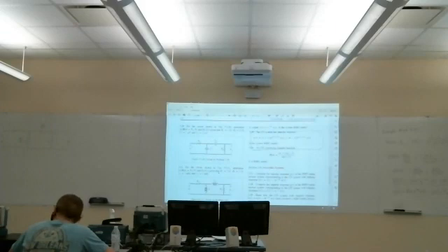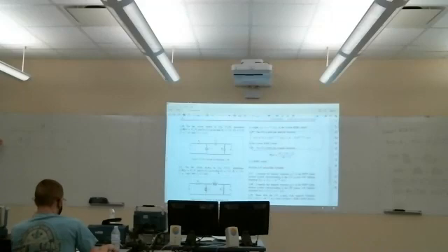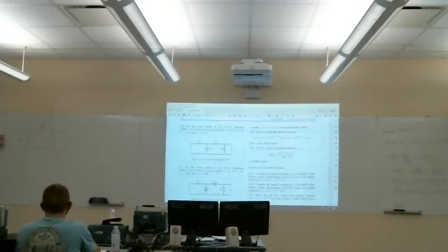Now to find the transfer function, you can analyze this, letting V1 be just V1 algebraically, and then use nodal analysis, leaving V1 as a variable and solve for V0 in terms of V1. The ratio would be the transfer function.